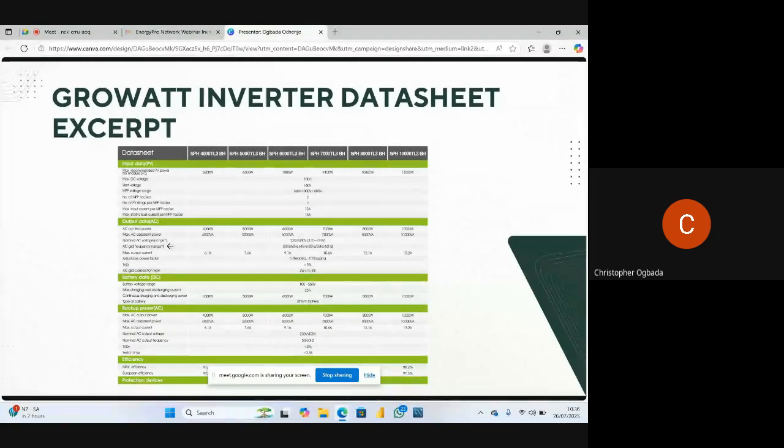So this is the output side. This is your maximum apparent power. You know, I told you apparent power. For this very inverter, the efficiency is very high. So you see that the apparent power is almost equal to the nominal power. So this inverter is giving you about 100%. You look at all these things, it matters. So don't go, for an inverter where the apparent power is not equal to that, is rated in kVA or VA, for example, and maybe the power factor is around 0.8, and you go and put 4,000 load. It's a problem.